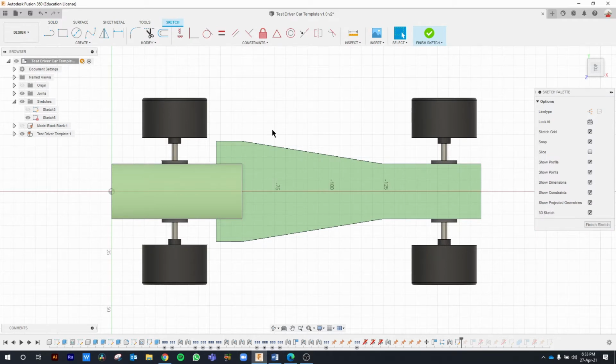Now let's start sketching our side pod. First, we need to start from behind the existing side pod by creating a line. So find your sweet spot where your mouse will automatically snap to the edge. Create a line till here. Click on the green check. Now we need to give our side pod a little bit of a curve.